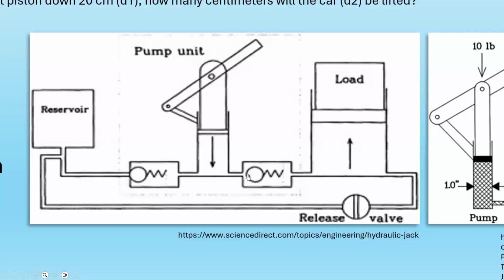It's installed the same way, but those two act differently on the downstroke, because this one is going to push this blockage out. The check valve is going to open, and the fluid is going to flow this way, creating a pressure in the bigger cylinder. So you can do a downstroke and just pump it. You're going to displace a certain amount of volume, and as soon as you stop applying pressure, that check valve is going to close, keeping all the medium from returning that way.